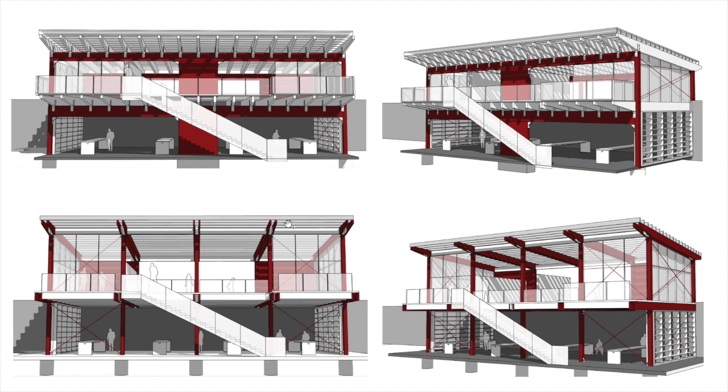For 2B, pretty similar strategy, except instead of having to brace it with a CLT in the middle, we're able to have thin bracing on the two ends there, opening up the whole middle space. In this case, you're putting that bracing there that defines the face of where that office space is on that side. And in fact, then the girders really lead you through the building. Breaks it up in terms of a planning module that's also a functional module, a view module. Is one right? Is one wrong? They're both right.